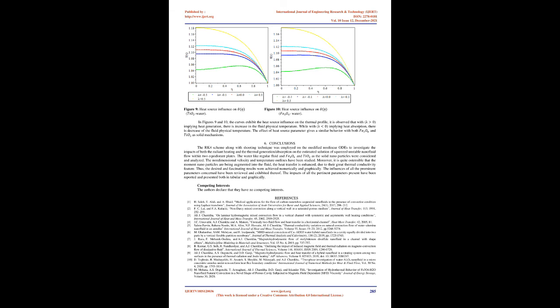Figures 4 and 5 show that for both Fe3O4 and Cu, as the magnitude of nanoparticles is added into the traditional fluid, this gives rise to thermal boundary layer thickness. It is noticeable that on growing the values of volume of solid particle the velocity boundary layer is thinned near the proximity of the plates, while remote from the surface of the plates it progressed. Owing to the great thermal conductivity of the solid particle, the heat transfer is believed to have been improved, while the thermal profile is anticipated to have declined. It is also noticed that the rise in thermal boundary layer thickness tends to occur faster with Cu than Fe3O4 when the parameter is being increased.